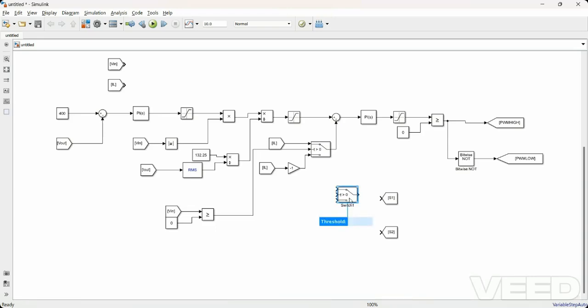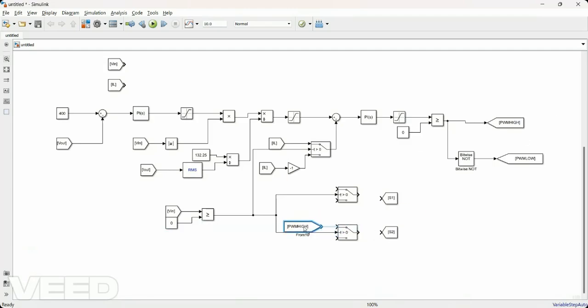Yeah, we have a switch here. All right, so the first thing is, if the voltage is greater than 0, then we are saying that S2 must be switched. So that means I take a PWM high, connect it here, and S2 is switched, right?